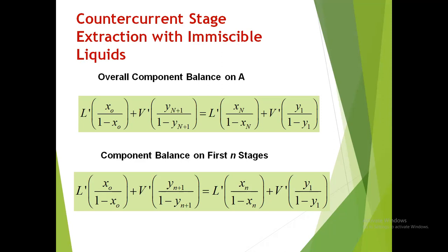You are making use of the inert part of the phases, the L prime and the B prime. L prime in this case for the feed is just the carrier solvent of your solute in the feed. B prime is to be viewed as the diluent for your solvent. Meaning, minus the solvent, what is the diluent present? That would be your B prime.